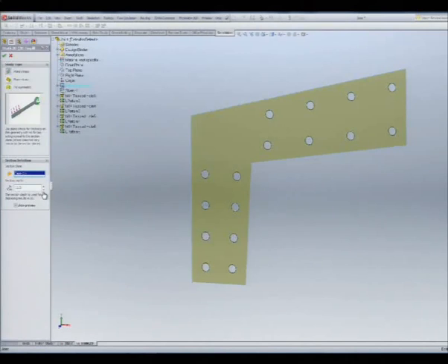Yes. There is something I'm missing in SolidWorks. You can link these values to the values that you have in the model. Use parameters, so that if you change the model, you don't need to change this by hand. So now you are inputting. When you do a shell, you end up saying which thickness. Yeah, half the thickness in the parameter. You can do this with CATIA too, you can use the parameter of the model to put it into the simulation, so that when you make a change in the model, you don't miss a change in the simulation.